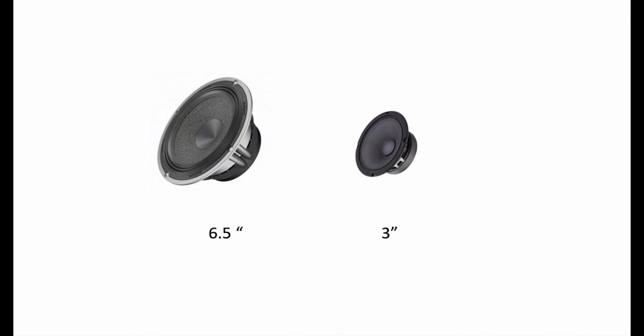Okay, so let's just take our 6.5-inch and our 3-inch speaker, and this time we want it to play 100 hertz. Now 100 hertz compared to 1,000 hertz is a much lower note, and to play lower notes you have much bigger wavelengths, and therefore you need to create more acoustic energy, which means more power, moving more air with every stroke of the speaker.